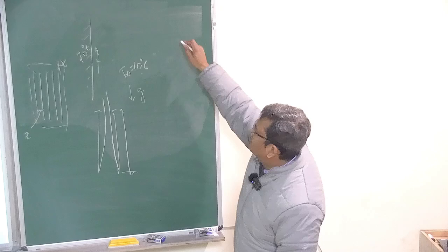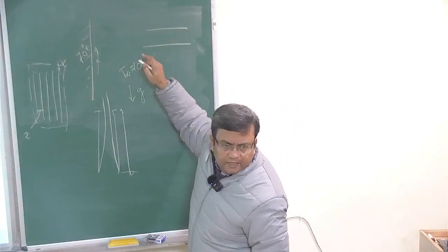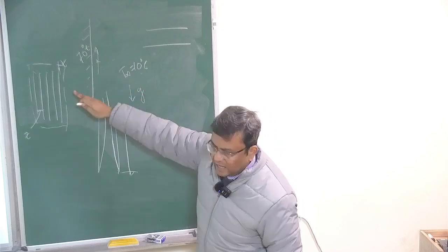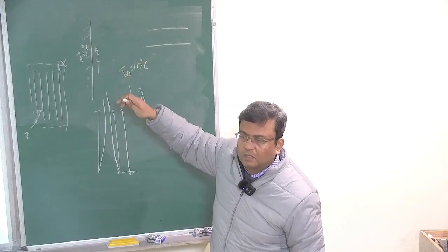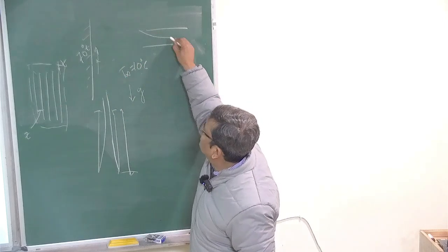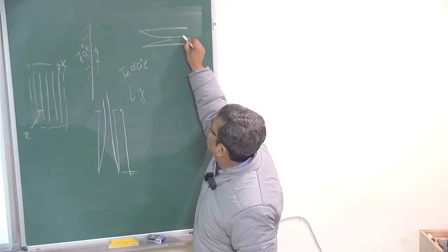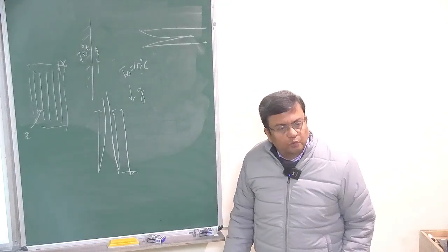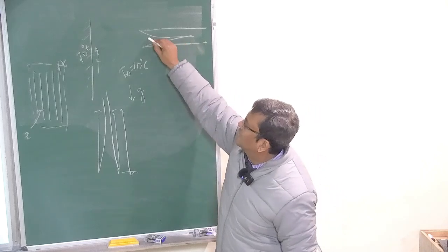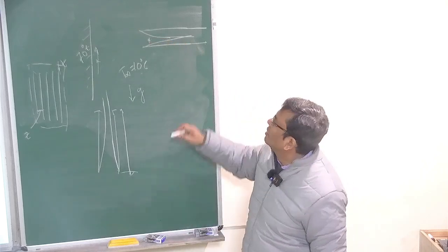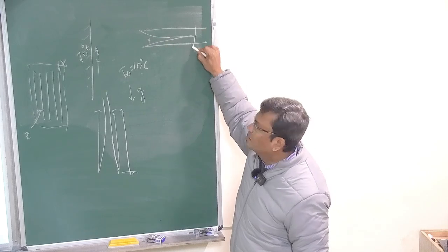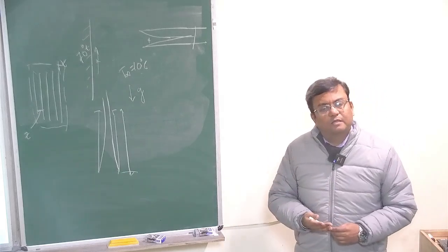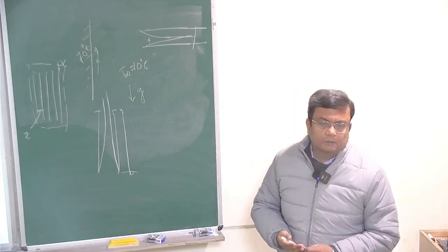let's say we just talk about one channel, one horizontal channel forced convection, which you're familiar with. Okay, this is natural convection, but I'm bringing up forced convection to remind you that at the entry region, the boundary layers go like this, and ultimately after they merge, we get fully developed flow, right? And the heat transfer in this region is actually higher or lower than here. This is fully developed heat transfer, let's say laminar flow between two plates. Which heat transfer coefficient is higher?